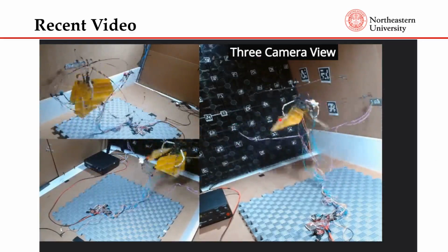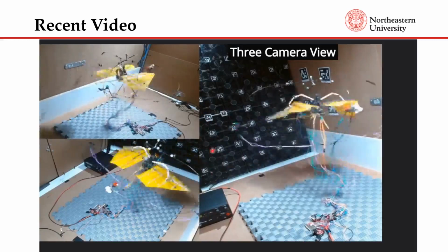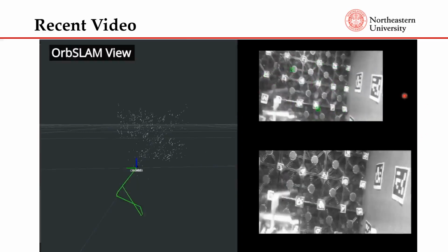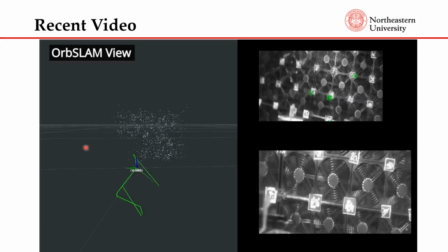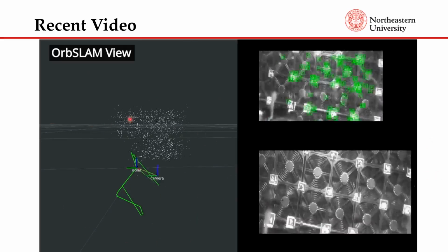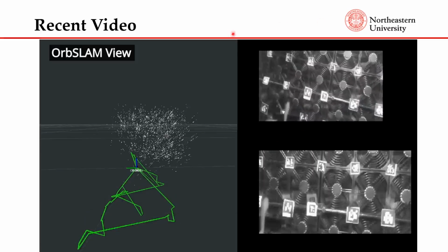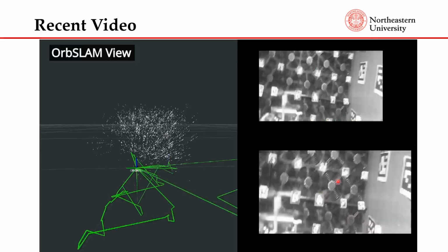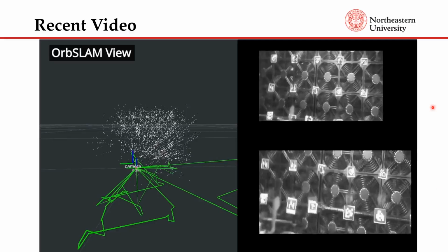It is equipped with a camera to detect all of these markers shown on the wall for localization and motion planning. This is a sample image and the estimation of the pose based on this detected image. You'll see it updated in real time based on the detected markers on the wall. It is flapping in front of these fan arrays, and it seems pretty stable with the assistance of the guard and the thrusters.